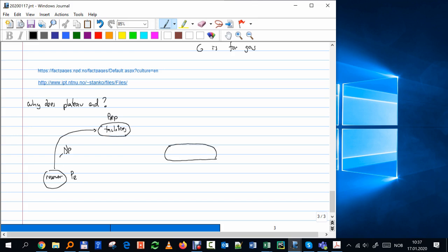So this is only the facilities. We are not looking at bottom hole or the rest of the system. We know we have to deliver at that particular point that has some pressure. We have to flow against that pressure, and that's the whole concept. I have here some pressure, the fluid has some energy, and then has to pay a toll, and then has to reach here. If I try to produce a big volume, this will be bigger. I have more losses along the system. Therefore, if I cannot pay that price with this energy that I have, then I simply have to reduce the rate, in a very simplistic way.